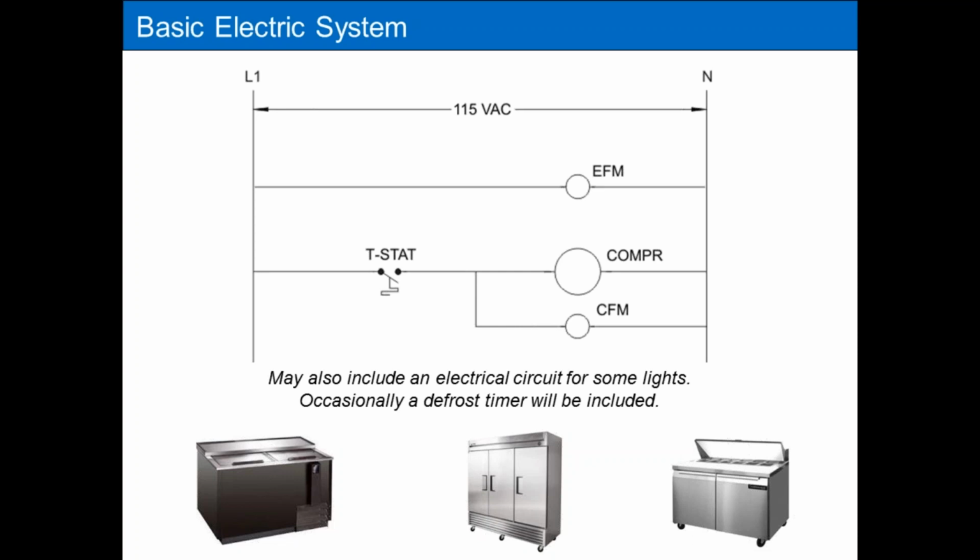I've seen some cases where the condenser fan motor has been wired to run all the time, either by design of a prior tech or by a manufacturer. So every once in a while you'll come across a condenser fan motor that runs all the time, and the compressor is the only thing that is cycling on and off by this temperature control. And you can verify that by looking at the wiring diagram to see if that's the way the manufacturer intended that system to work, or if a technician prior to you getting there rewired the system so the fan ran all the time. So watch out for that subtle possibility.